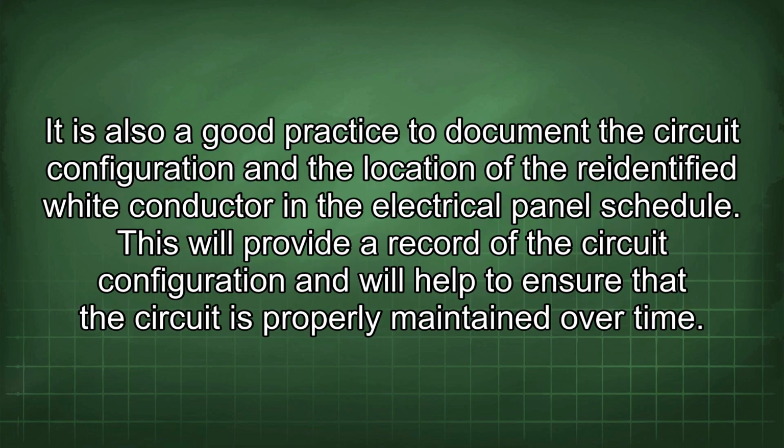It is also a good practice to document the circuit configuration and the location of the re-identified white conductor in the electrical panel schedule. This will provide a record of the circuit configuration and will help to ensure that the circuit is properly maintained over time.